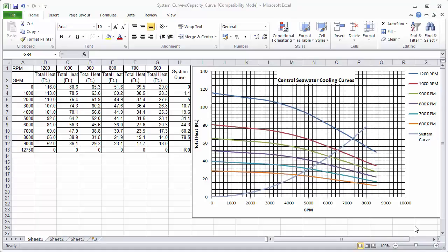We were evaluating a system which had a set of centrifugal pumps. The pump capacity curve data was based on an operating speed of 1200 RPM, and they needed to consider the speed of the pump at 600 RPM. They therefore used their Excel template file as seen here to determine the adjusted performance curve for the pump based on this revised speed. The designer quickly noticed a difference between the capacity curve generated by FluidFlow versus that they had created in their Excel file.